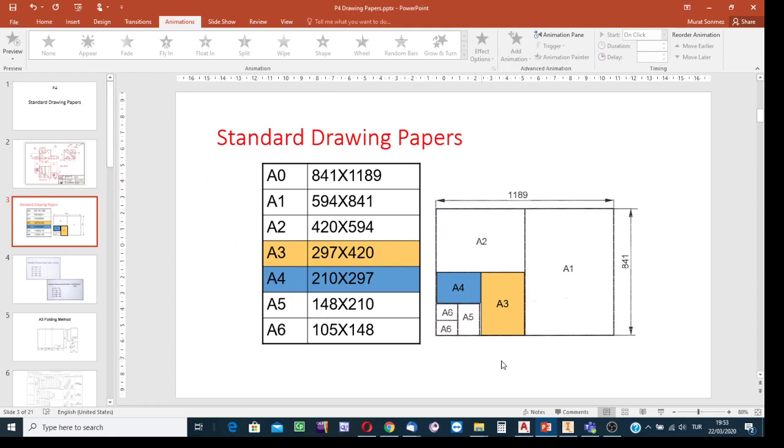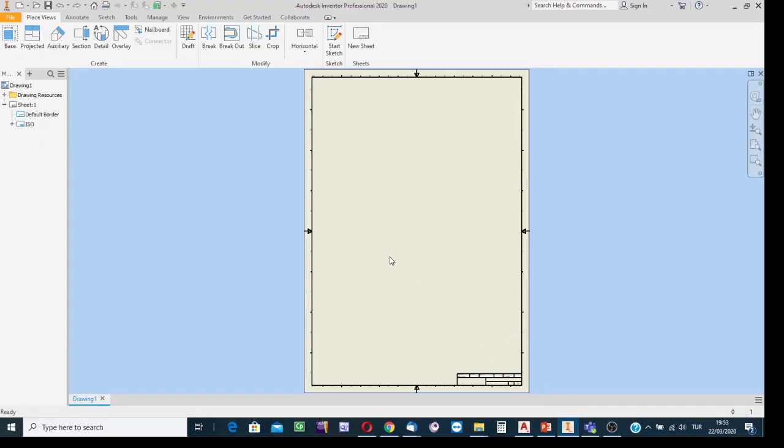And say that in the example, the necessary views to have are not only front but also top and left. So it is obvious that under the scale factor 1:1, it is impossible to fit the images over an A0 size paper. Okay, well, A0 is the basic largest size. This does not mean that we cannot use an A0 size paper.